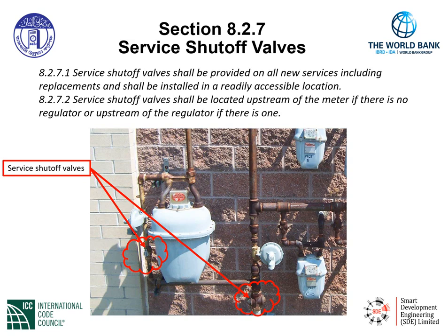Service shutoff valves. We have two requirements that indicate service shutoff valves be provided. And where are they to be located? In section 8.2.7.1, we need to provide service shutoff valves on all new services, including replacements, and they need to be installed in a readily accessible location. As we can see in the picture below, we have service shutoff valves.